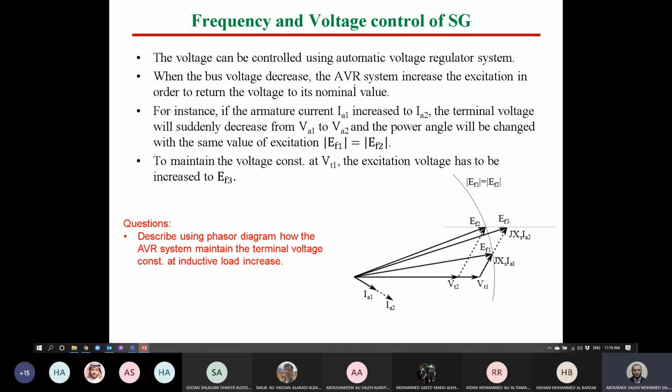Okay? Fine. In power plants, what has happened? Of course, due to the high power generators in power plants, we have to use this system, AVR. And this is the reason why the grid voltage is constant, because there is all the time an AVR system connected to all of the generators, which makes the terminal voltage constant. So this is the reason why the terminal voltage is constant for all grids. Okay guys? Because there is an automatic voltage regulator system or controller.